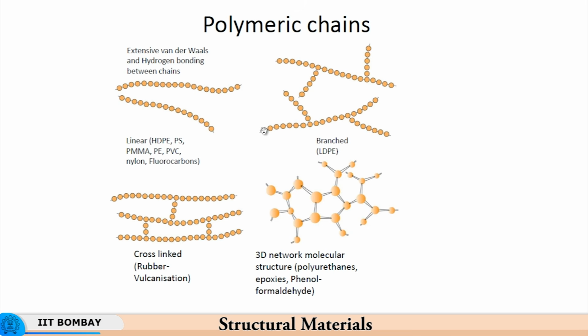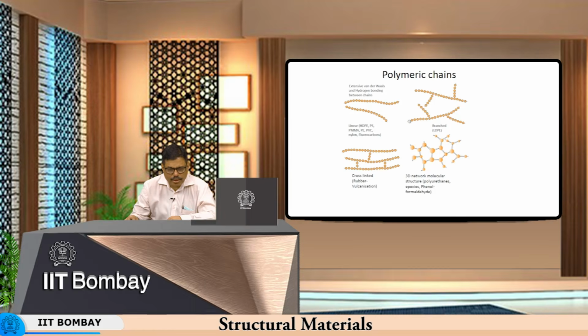and then the chains tend to be more or less parallel. But then when they are brought together, as you see here, there will be a resistance for the chains to come together as a result of the hydrogen atoms preventing the other chain from coming together, and therefore you need a greater amount of force to force these chains together, and therefore once the force gets removed, the deformation gets recovered.